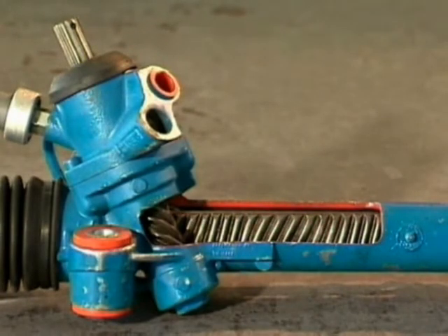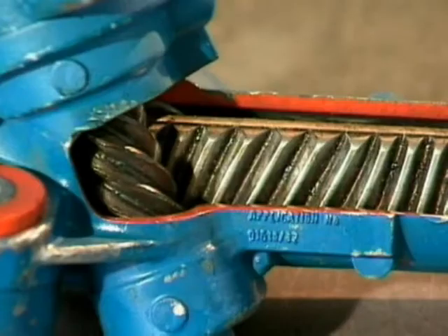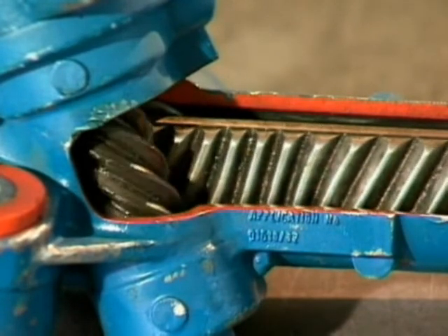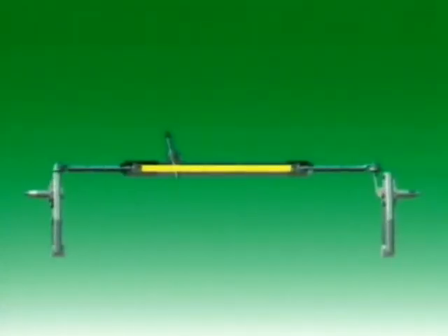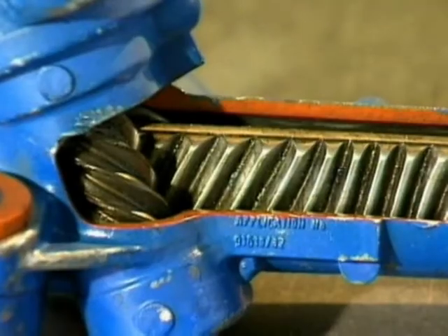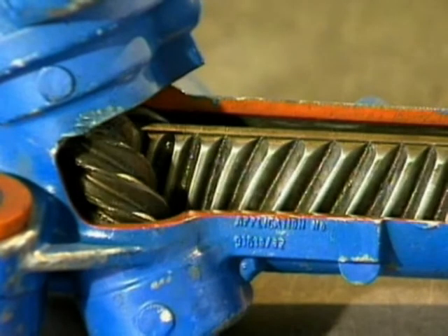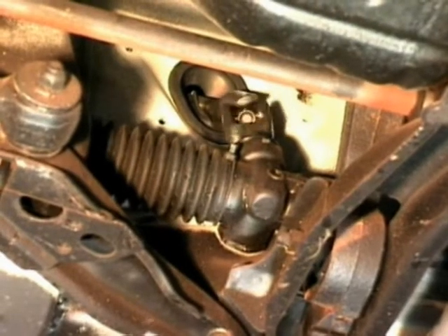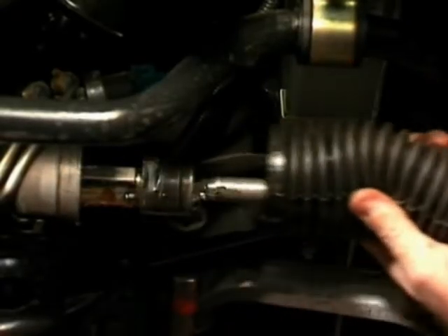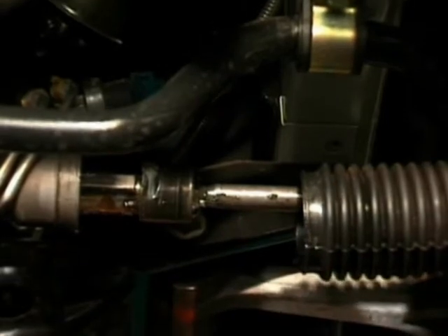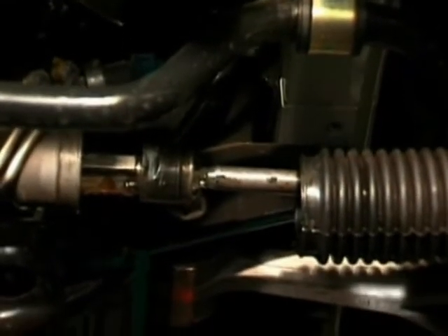This section examines the rack and pinion gearbox. The rack and pinion steering gearbox has a pinion connected to the steering column. This pinion runs in mesh with a rack that is connected to the steering tie rods. This gives more direct operation. Both the pinion and the rack teeth are helical gears. Helical gearing gives smoother and quieter operation for the driver. Turning the steering wheel rotates the pinion and moves the rack from side to side. Ball joints at the end of the rack locate the tie rods and allow movement in the steering and suspension.